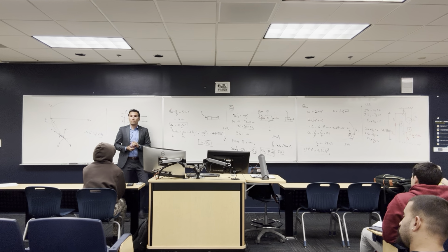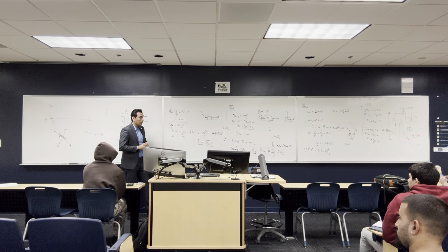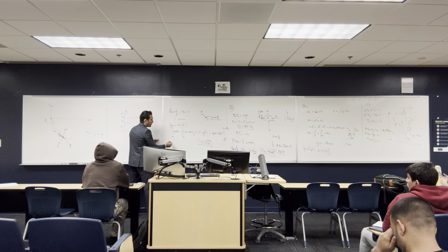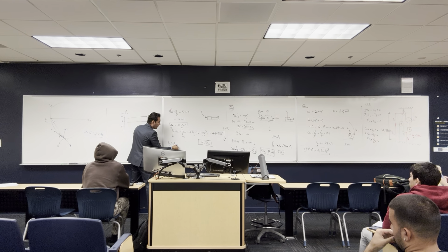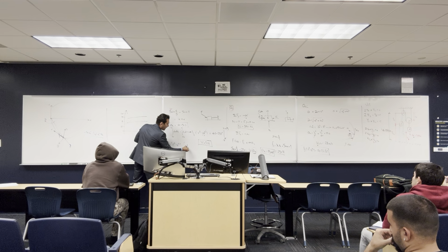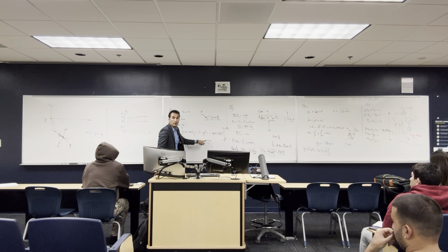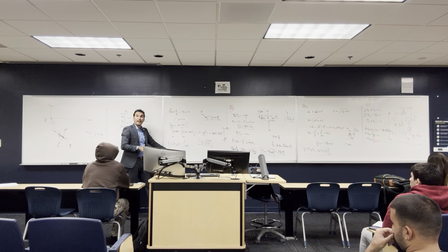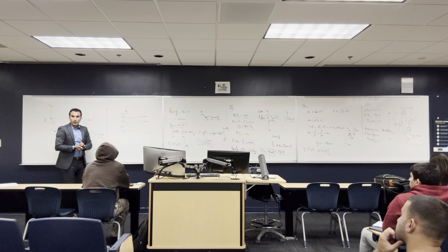Would it have been possible to get the same velocity on the non-constant process from the kinematics? That's what I did, that's the kinematics. So this equation is the base for this. If you look at your equation sheet, you will find an equation, half v squared minus v node squared is equal to the integration of A dS from S node to S. That's this equation, so that's the expansion of it. If A is constant, and I told you it's constant, but it's never gonna be here because there's a spring, I would take A out. Okay? All right. Does anybody have any other questions?